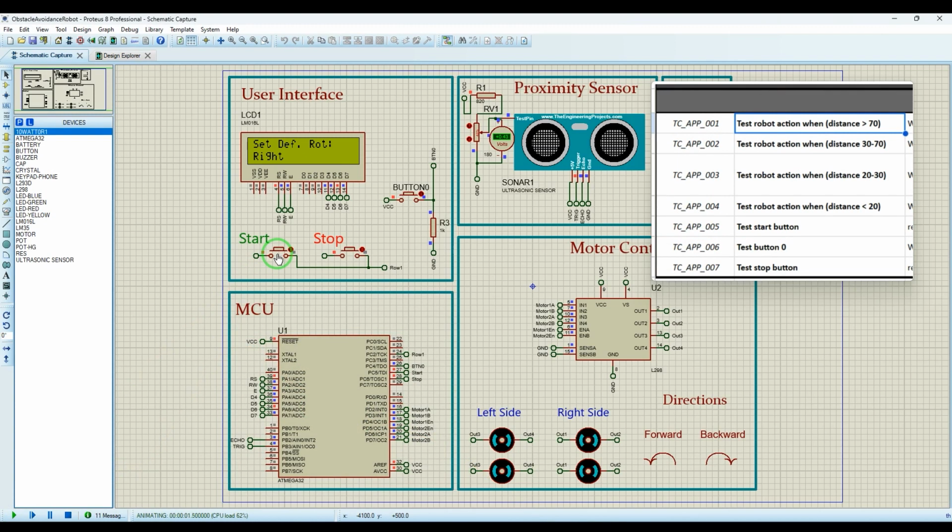Quickly pressing start, you can set the default rotation here for 5 seconds. After the 5 seconds, it will time out. If you click stop, it will just revert back. If you click start again, it should remember that we want it left. That's an extra, so it does remember. You can also change it again, so choose left and wait for the 5 seconds timeout. Starting direction left, 2 seconds, and then it will start moving.